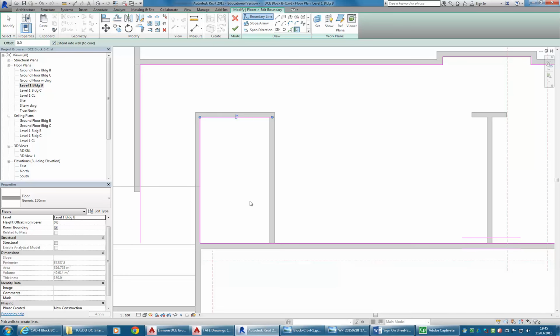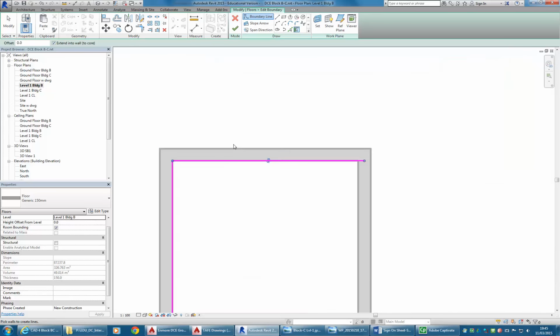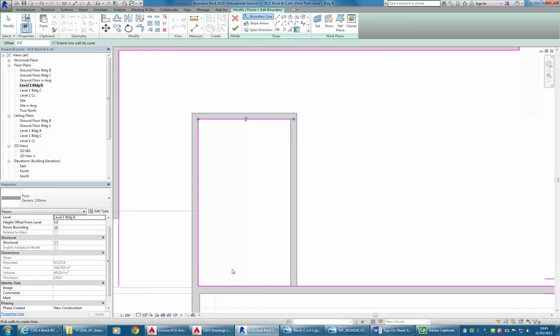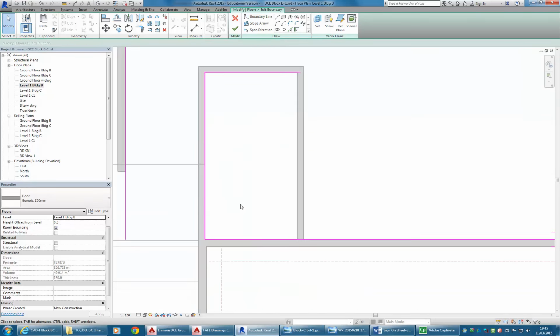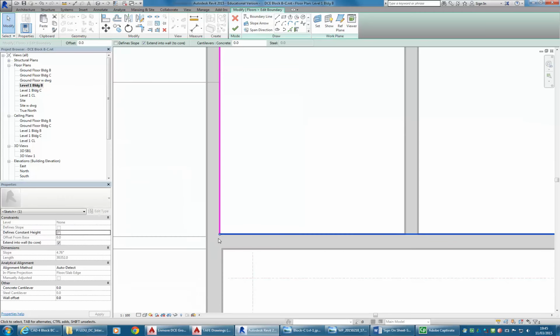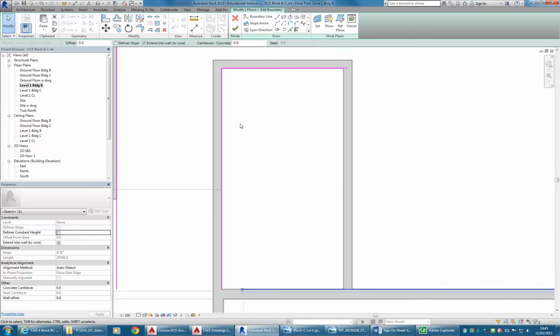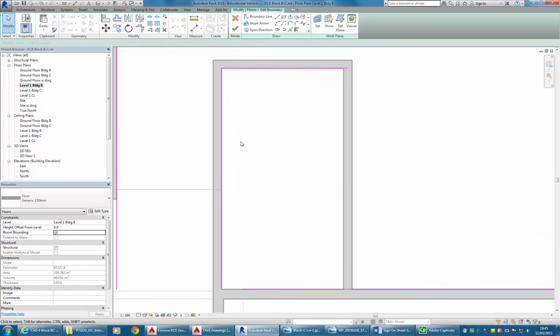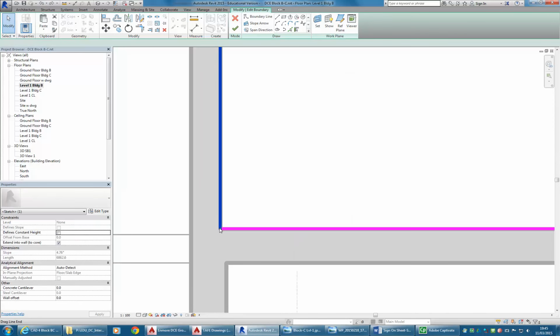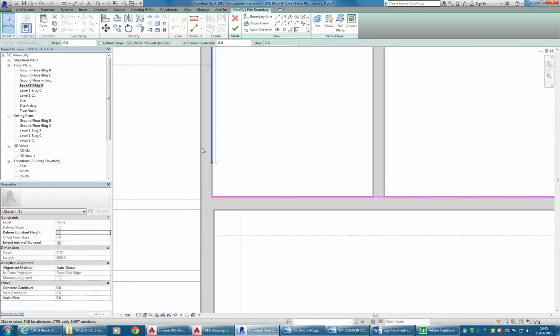So I'll undo that. I definitely want this line on the top, but I can't just flip it because it's taking other lines with it that I don't want. So the secret there is to just drag the end of this line, for example, away from the others. Or I could have done the other one, so I could have dragged this one up, so they're no longer connected.